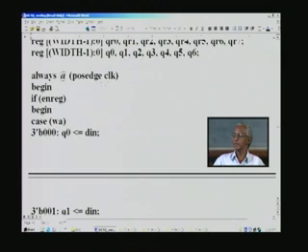And in this block, what we are going to do is simply assign the data in value to different registers depending upon the write address, and the write address is also one of the inputs. If the address is 000, then we take whatever is the input at data in and merely copy it into the Q0 register. Like that, Q0 through Q6 will be used for different addresses, and before this we can do all this only so long as this chip is enabled, that is, enable reg is one of the inputs, and this in turn is from the enable counter 2. Only if it is enabled this will take place, and with the arrival of the first clock this write address will be 0, and with the next clock it will be 1.